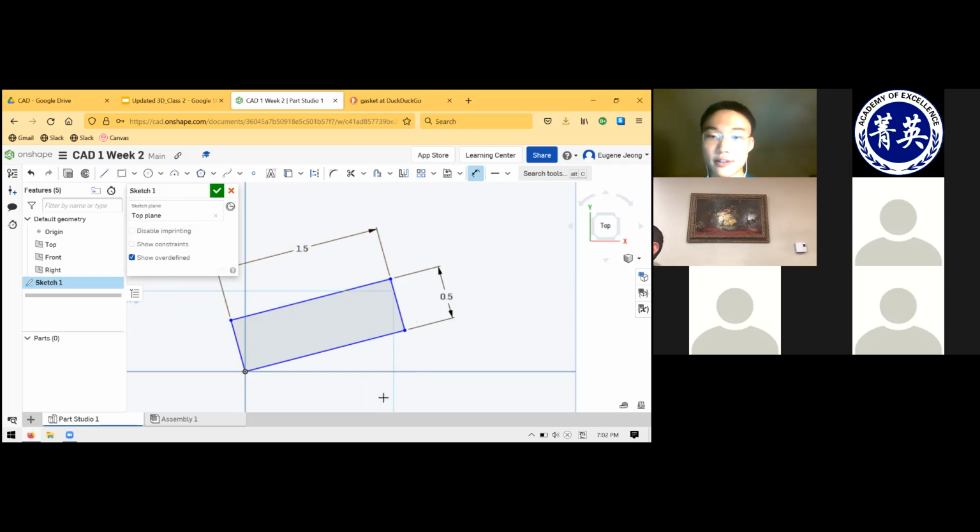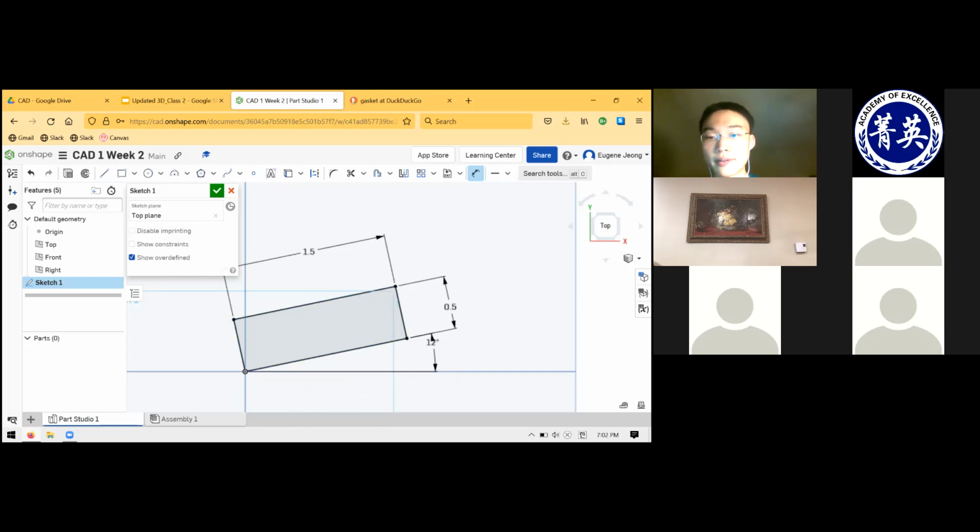just length. And so the way you do that, you select the tool, you select the thing that you're trying to dimension, and you select the other kind of reference that completes the dimension. In this case, that's our x-axis here. So if you carefully put your cursor above this horizontal, faint line, that is your x-axis. So you can click that actually, and then it'll turn it into an angle type of dimension. And you can type in a number. Same as the length dimension.